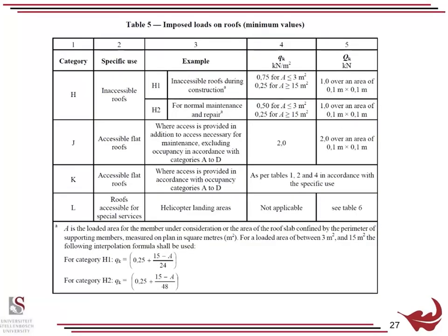And so now continuing on, inaccessible roofs. What's an inaccessible roof? Well, that's where it's difficult to get up there, so chances are people won't use it to have a balcony party up there. It's not readily accessible, so you wouldn't have large numbers of people up there. It's really basic access, up a cat ladder, and then you wouldn't be able to store equipment up there easily. Whereas an accessible roof is not too difficult to get up to, so maybe people would store material there, maybe you would have a social gathering up there. You'd have to be a bit more careful.